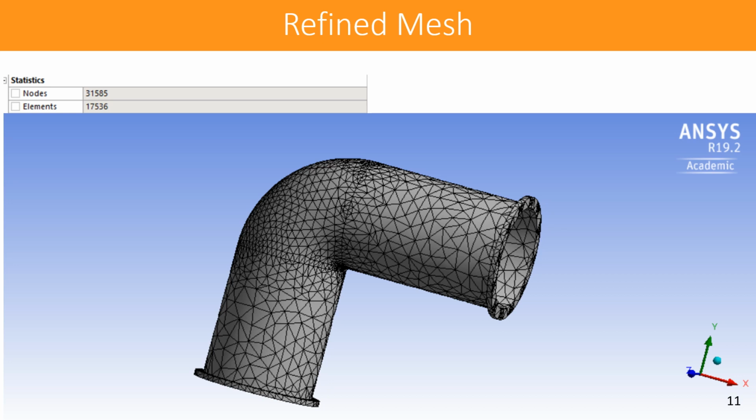So applying a refinement to the mesh in ANSYS, I found that due to a difficulty with my license, it only allowed me to apply the refinement to a select few parts of my geometry. I couldn't apply the refined mesh to the 2 long tube sections, and the most relevant place that I was able to put it was on the curved elbow.